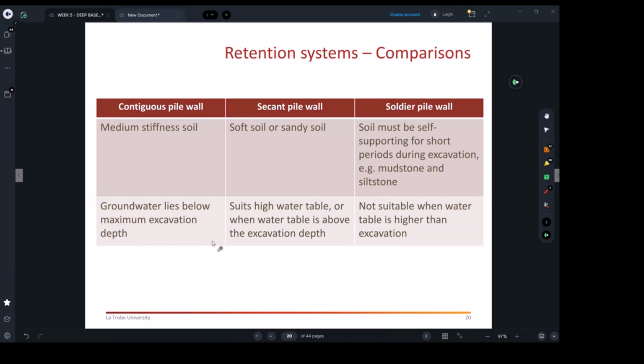But as a builder, it does not mean you have to blindly just go and hit and smash. You need to make sure the conditions assumed are correct. The role of a construction engineer is, first, to understand what the documents are saying. Number two, they need to make sure what is written in the documents is actually what is happening on site. Don't just assume, because the soil report will always have notes saying that is what they inspected.